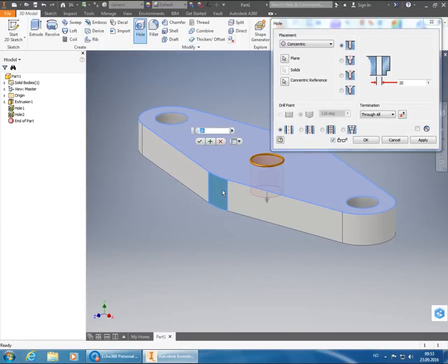So if you were doing this with extrudes, you would have to first create one of the holes, and then you would have to create the counterbore. But since we're using the hole function, we actually have the option of doing everything at once here. So instead of using a regular drilled hole, as we have up here, we go down to using the counterbore hole.